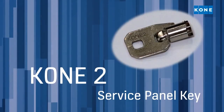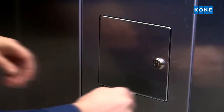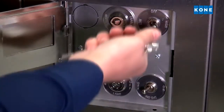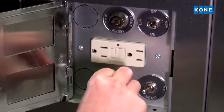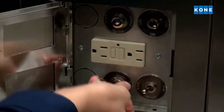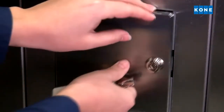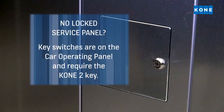If your elevator is equipped with a service panel, the KONE 2 key will be used to open the service panel door on the inside of the car near the bottom of the car operating panel. Inside the panel, there are both key and toggle switches that operate the car fan, car lights, and independent service. Again, these may vary depending upon your elevator's features. If your elevator does not have a locked service panel, the key switches for the fan, lights, and independent service will be on the car operating panel and will require the KONE 2 barrel key to operate.